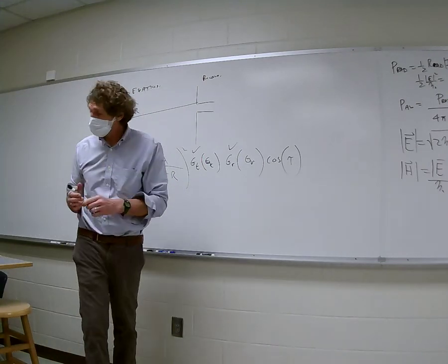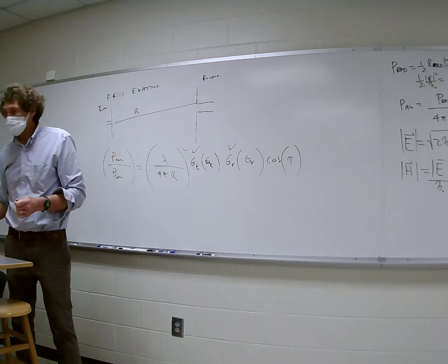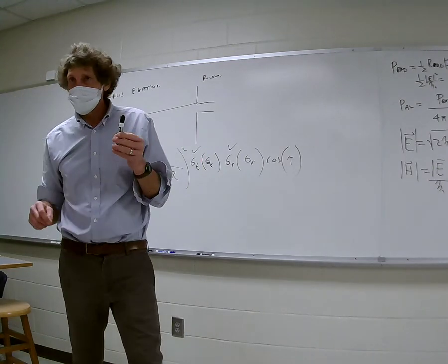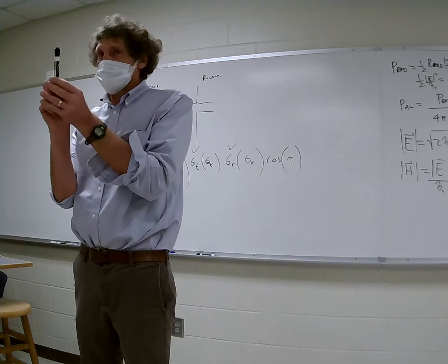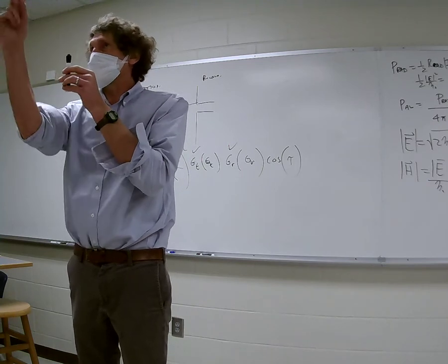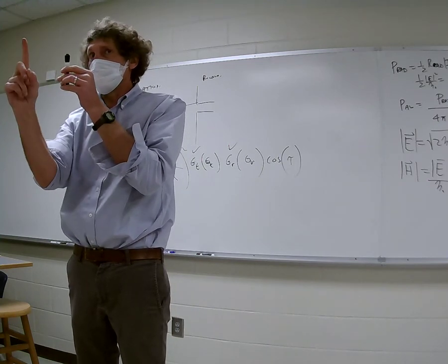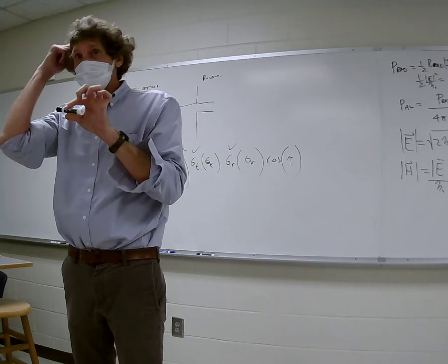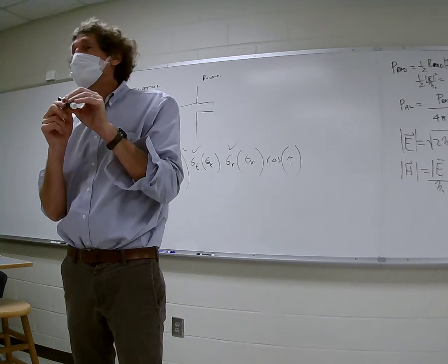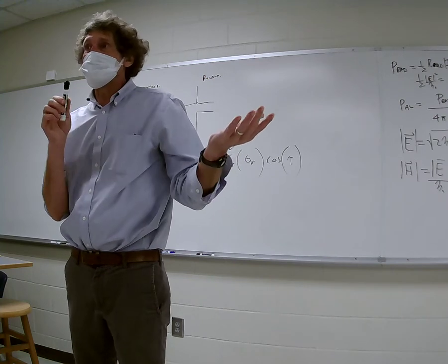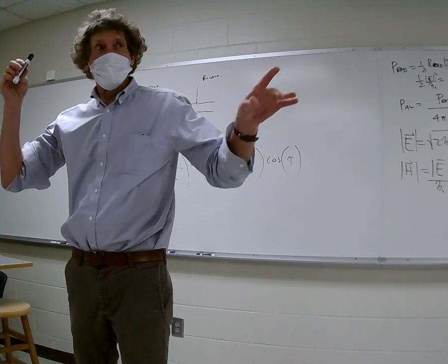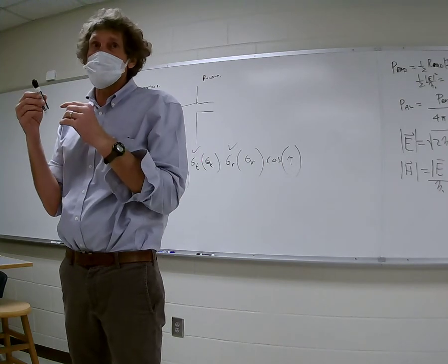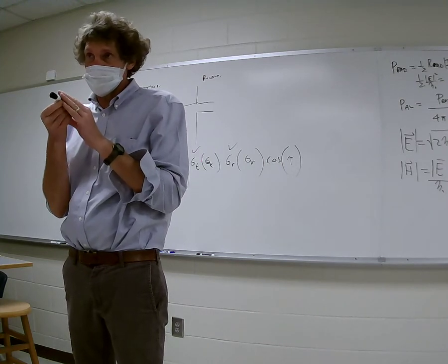And that's very important when you have antennas, because I have seen this personally. If you try to receive a signal, and you're in free space, say, and you got an antenna transmitting a vertically polarized E field, with an antenna this way straight line, you get zip, and you're scratching your head by the way this happens. Now, usually if you're in an environment like this, you'll get something, because the waves ricochet all over the place, and the reflections do have a component of polarization in the direction of the antenna.